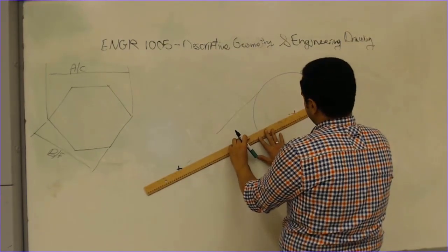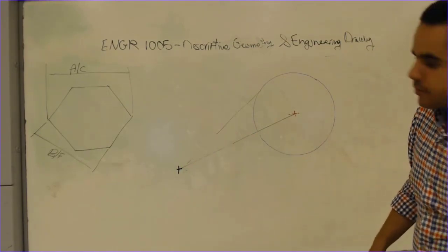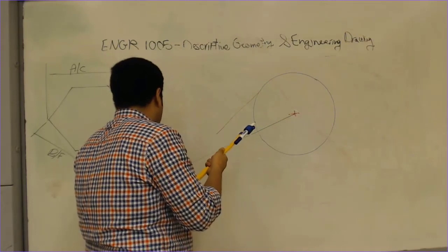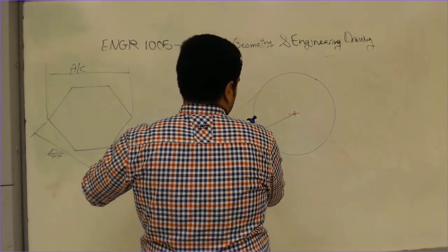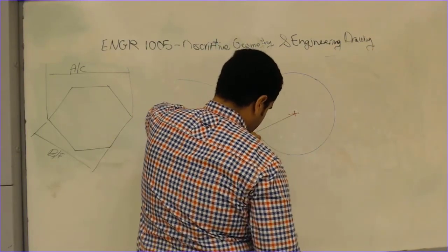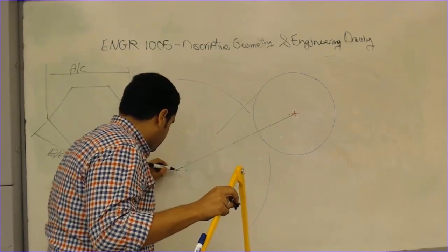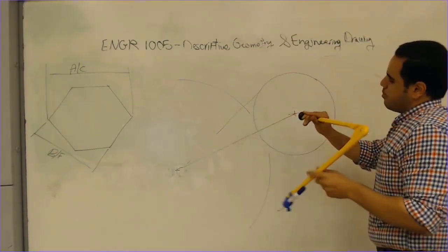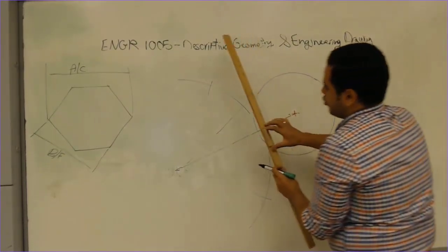All you have to do is to connect both points, which is my point here and the center. Okay? And you find the bisectors, if you remember from the beginning of the video. We place the compass here, and we open the compass on a slightly larger distance from the center point, here and there. Okay, and with the same opening, the same dimension, we place the compass here and we find the intersection here and there. And if you connect the two new points like this,